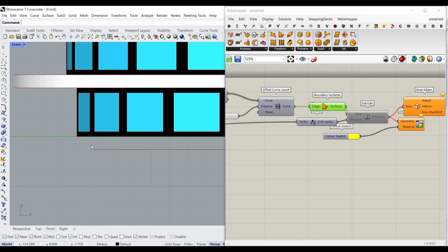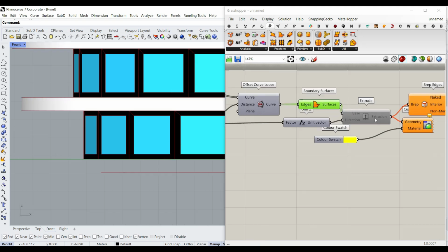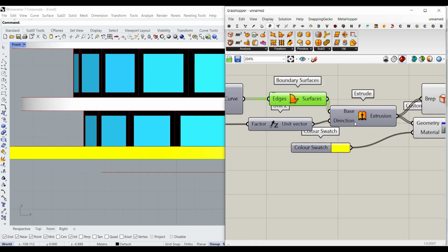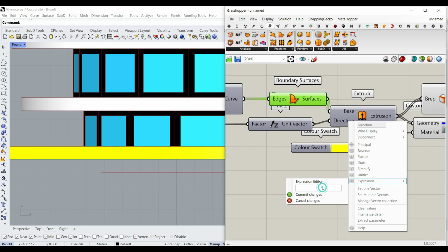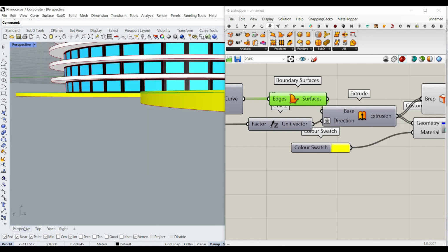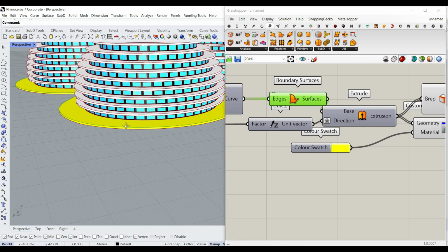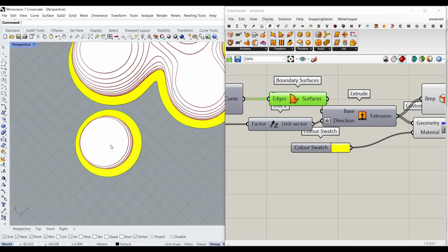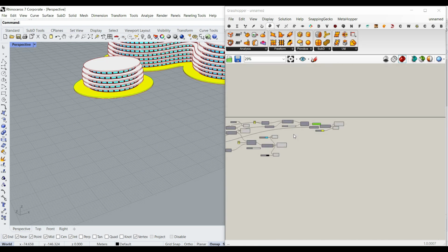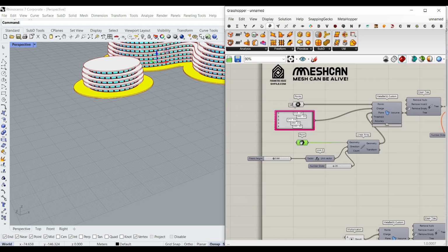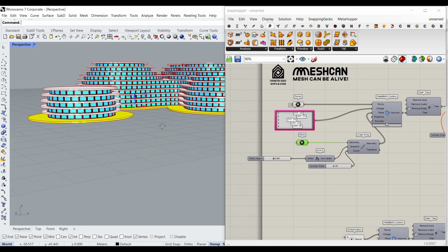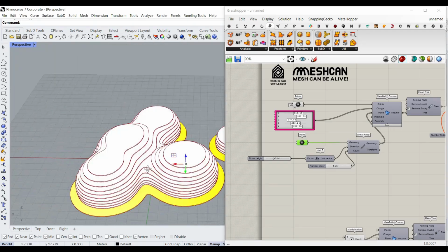At the end of this tutorial, I guess that we had to give this extrusion downwards, so I'm just going to give that -6. I forgot that it's going to go down anyway, and that's the last trick I wanted to explain. And if you get those points separate, remember to play around with the point of intersection. This is going to affect the final results, and you can get the outputs as in this tutorial.